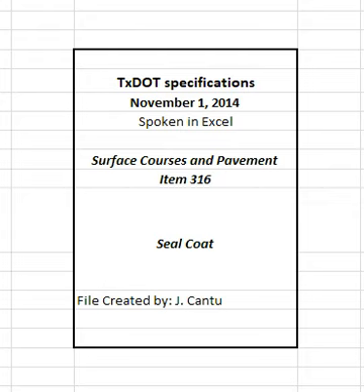4.9 Aggregate placement. As soon as possible, apply aggregate uniformly at the rate directed without causing the rock to roll over. 4.9.1 Non-uniform application. Stop application if it is not uniform in the transverse direction. Verify equipment condition, operating procedures, and transverse application rate. The transverse application rate should be within 1 pound. Determine and correct the cause of non-uniform application.